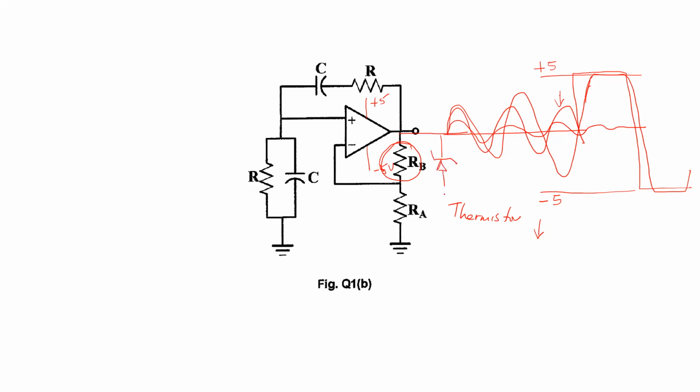back-to-back Zener diodes. Right? So you put the Zener diodes on the output. So if this was VD1 and VD2, as soon as the output here exceeded the value of VD1, that particular Zener diode would start to conduct and prevent the amplitude from getting beyond that.